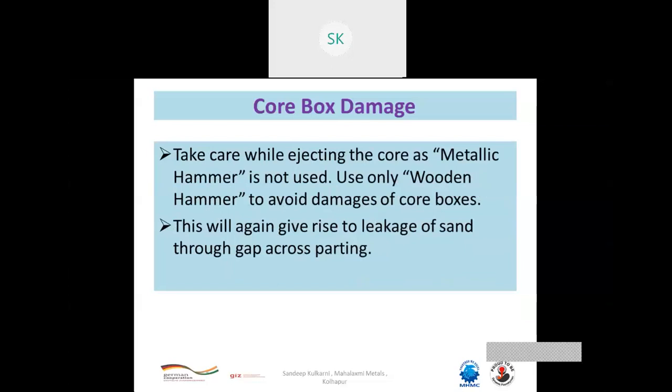Another type of damage is because, when we are releasing the core, sometimes we have to use a hammer, and during this activity, people are using metallic hammers or ferrous hammers or cast iron hammers or steel hammers. So it is a very dangerous thing, because it will damage your core box heavily, particularly the corners of the core box. And whenever you close the core box, there will be some gap at the corner, which will allow the sand and amine to flow outside the core box, and it will not give you a good finish of the core. It will give a lot of smell of amine outside.